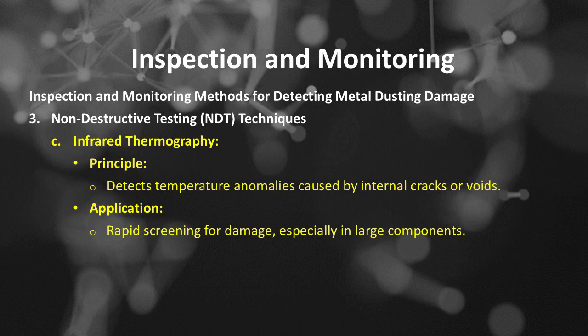Number C of NDT techniques is infrared thermography. The principle of infrared thermography is to detect temperature anomalies caused by internal cracks or voids. Application of infrared thermography is rapid screening for damage, especially in large components.